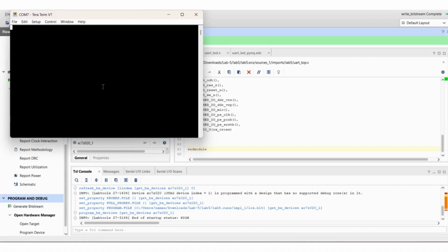Ideally all 8 LEDs would show this pattern, but the PYNQ-Z2 board has only 4 onboard LEDs. So the lower 4 bits are connected to the onboard LEDs, and the upper 4 bits are sent to PMOD pins, which are not visible unless external LEDs are used. So we only see 0001 in case of capital A.